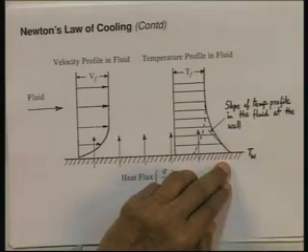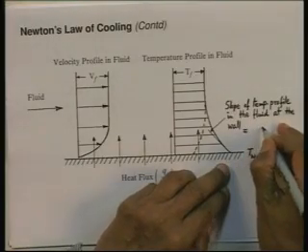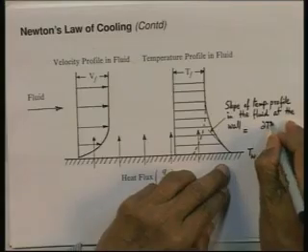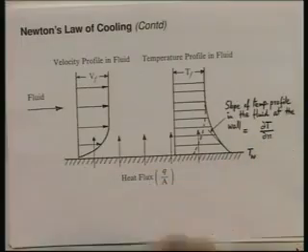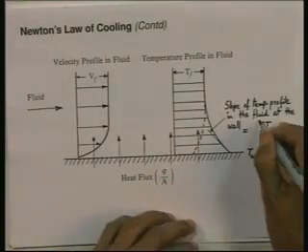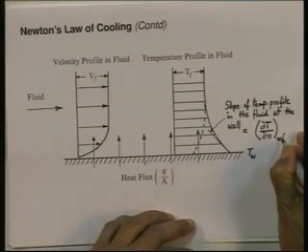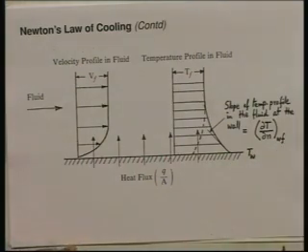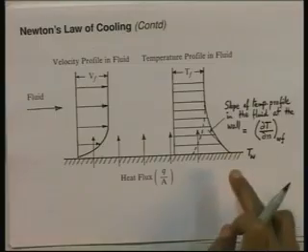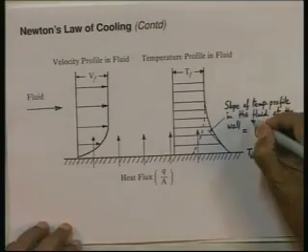That is what we have got here, and we can symbolically write it as equal to dT/dn, where n is the normal direction to the wall, evaluated at the wall, w, in the fluid, f. W stands for the wall and f stands for the gradient in the fluid. All right. So, dT/dn at w,f would be the slope of the temperature profile in the fluid at the wall.